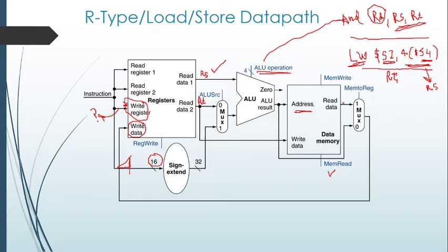That data is passed to be written back to the register via the same multiplexer, but this time the mem2reg signal will have a different value, because the data to be stored in register RT is coming from the memory. This completes the load word instruction with a write operation on the register file.